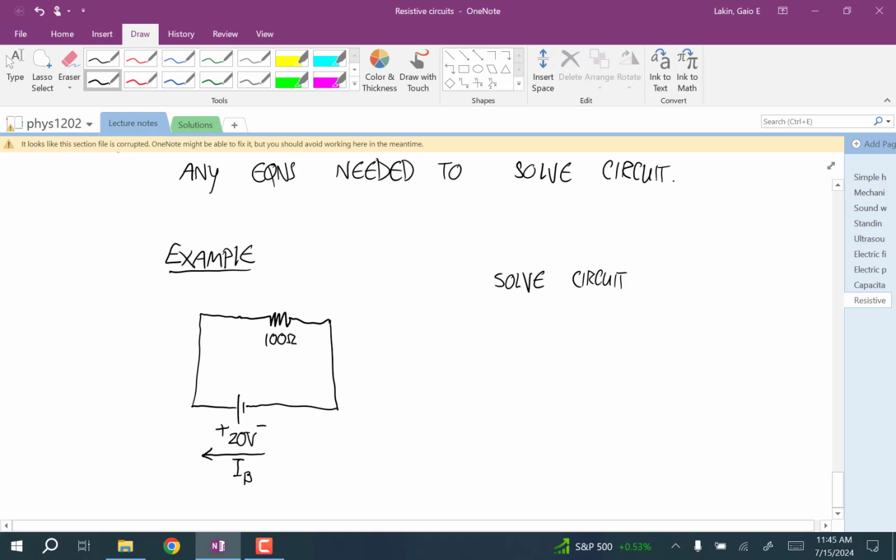And if the fluid is going this way and it hits a constriction, the flow is still going to go this way, so I'll call this IR. And then the polarity always has to go plus to minus in the same direction as the current at a resistor. So there's the plus, there's the minus, and now we've chosen our directions.